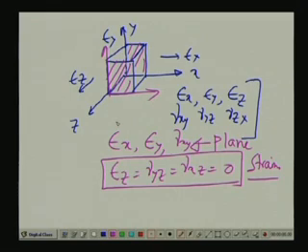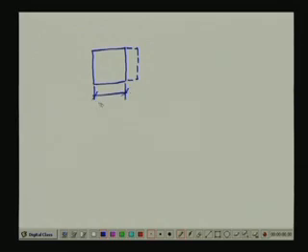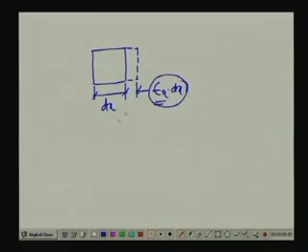Now, in this plane, if we like to find out the strains corresponding to 3 different directions. Now, if we consider the material in this particular plane only, in the x direction when it is stretching, it is undergoing deformation in this particular direction, and if we say this length as dx, then it will undergo stretching epsilon x dx, epsilon x being the strain, dx being the original length, then the elongation is epsilon x dx.